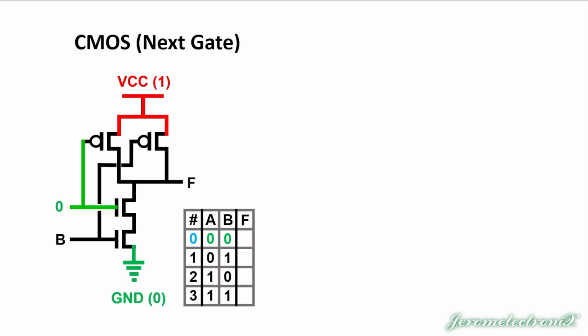That is flowing in two directions. It flows up to the PMOS, and what that means is a 0 in the PMOS means that the PMOS is going to allow flow. Down on the other NMOS gate, a 0 blocks the flow. So you can see that the flow has gone from the VCC out through F. You put a 0 into this mystery gate, and you get a 1 out of it. Okay, but we've still got the other input to do.